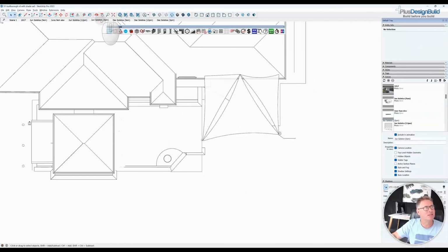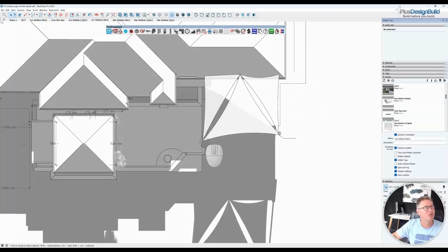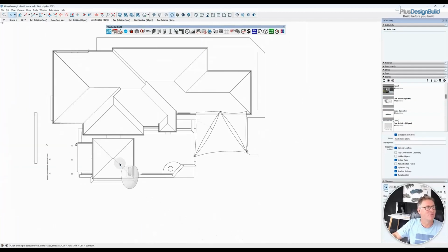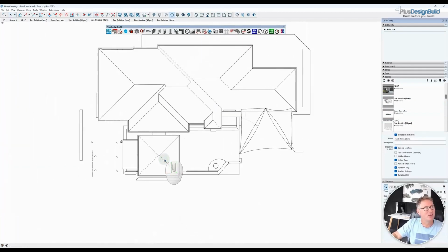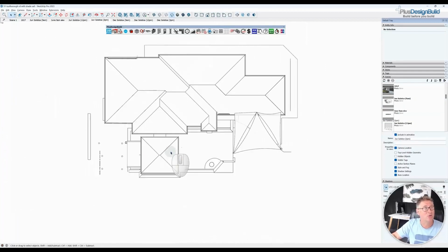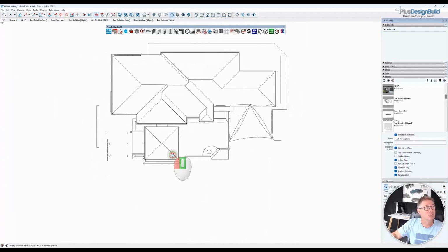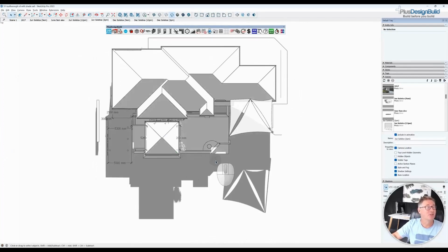Now, one other thing you want to look for here is your longest shadow, because you'll notice that this one, once I get it in the center of my screen, is going to be the longest shadow. And inside Layout, you want to show the total distance the shadow is cast. So I'm going to show you a little trick here that's going to help you out. This is where I want them all to be shown like this. So I'm going to right click and update my scene.